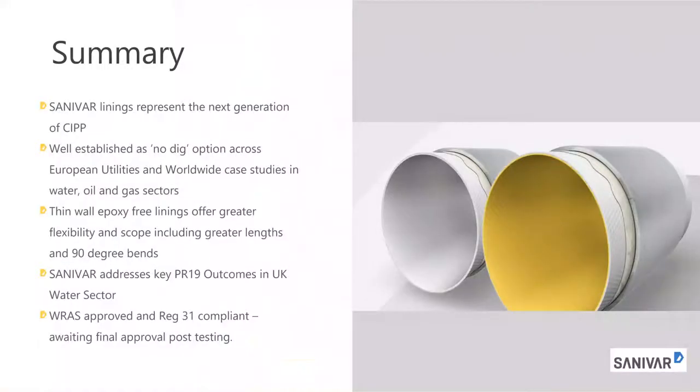So in summary about Sanivar in general, our linings represent the next generation of CIPP. It's well established as a no-dig option across European utilities, and we have worldwide case studies in water, oil and gas sectors. It's thin wall epoxy-free linings, flexibility and scope, including lengths and complex pipe configurations. The Sanivar liners address key PR19 outcomes in the UK water sector. The liners are RAS approved and they are Regulation 31 compliant.